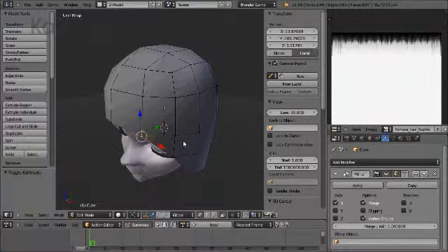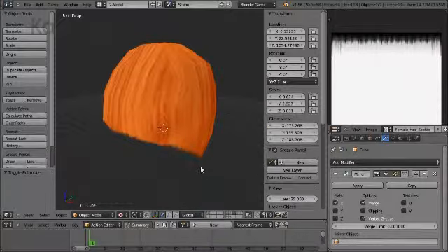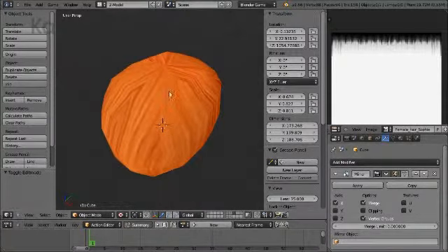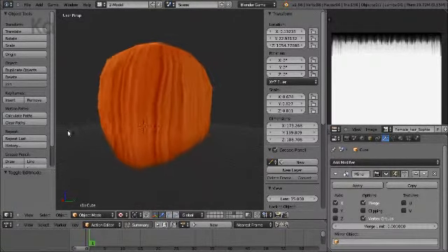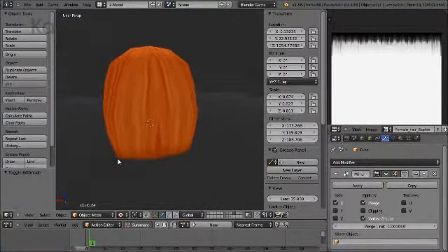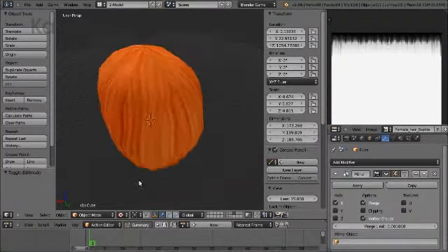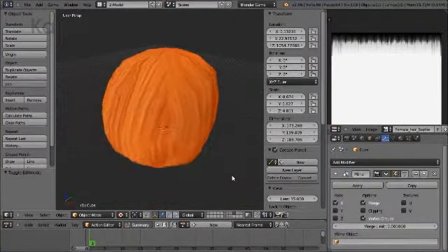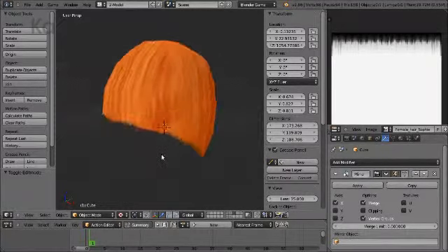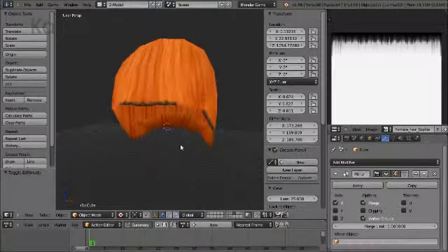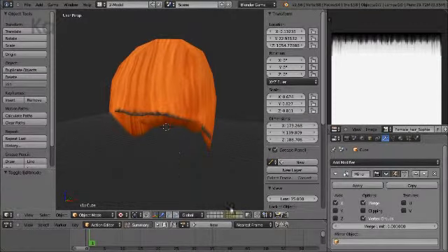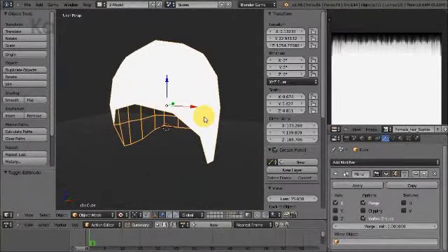So you need to avoid unwrapping that goes against the grain as much as possible, or against the direction in which the hair naturally would fall. The general principle of unwrapping is to keep the direction in which the hair falls and reduce the number of crossovers or intersections or general misshaping that occurs as a result of overlapping or split UV maps.